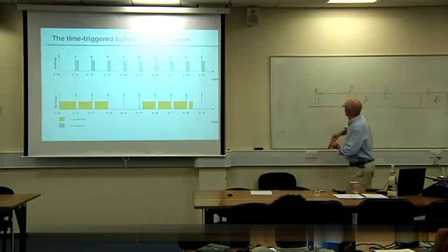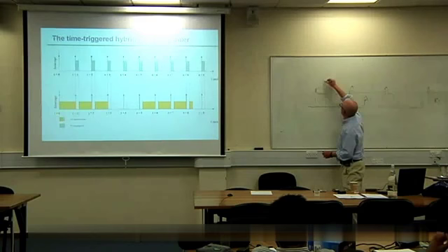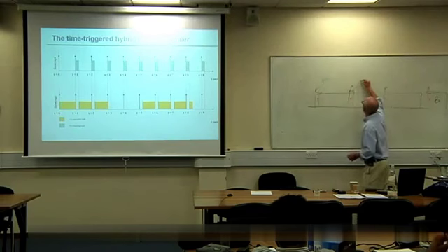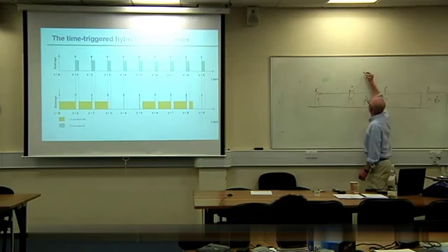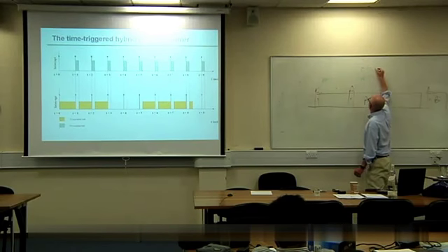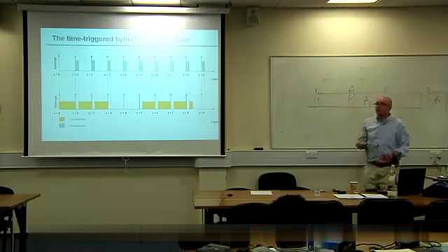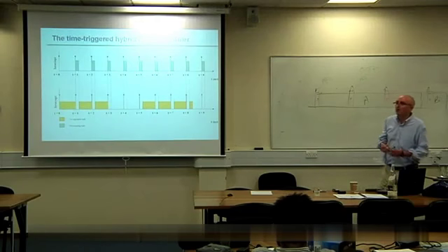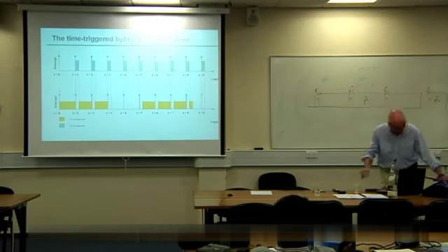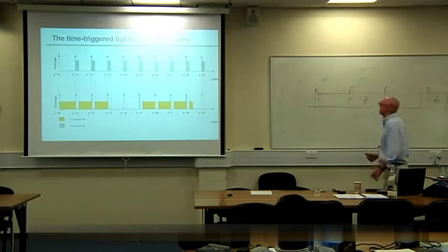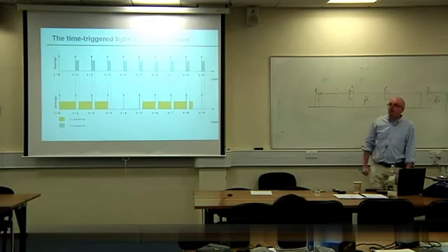Suppose this is an ADC task, and I've got a 0.01 microsecond requirement on the jitter in my ADC sample, which is not a million miles from possible reality. So I need to get the timing of that task really pretty precise.